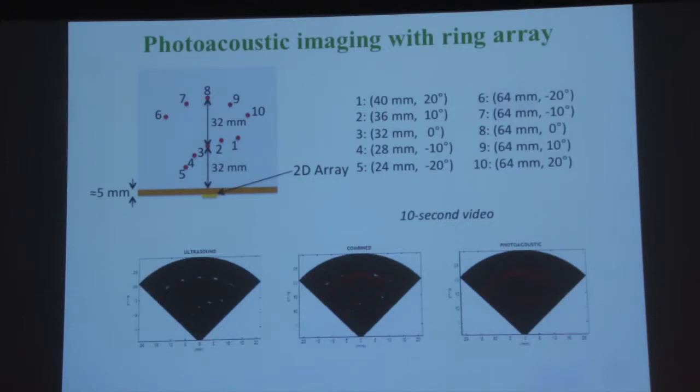The reason for this is when you do imaging with the ring array for anatomic application, we use something called Norton weightings. So you weigh the aperture as you transmit, and in receive, there is no such weighting. So we're working on trying to figure out the theory of how to do weighting on receive to reduce the side lobes in photoacoustic imaging in this part.